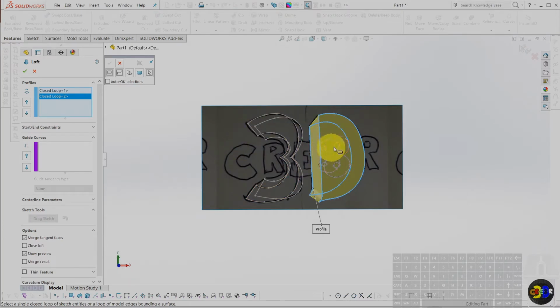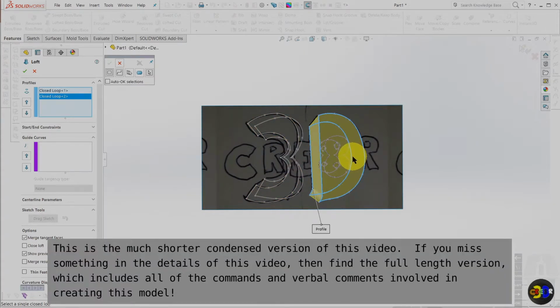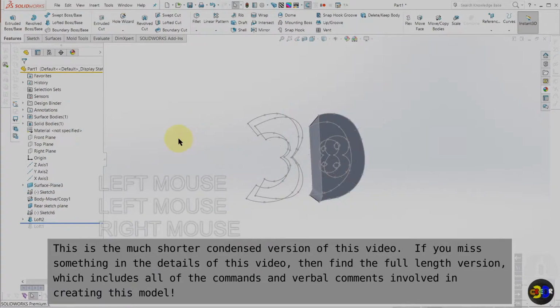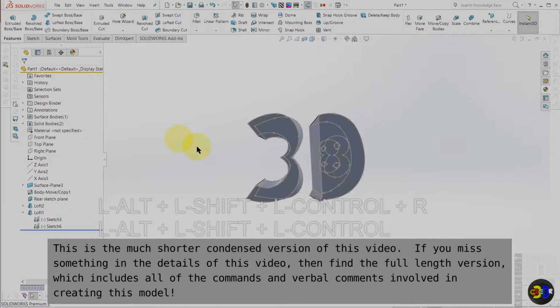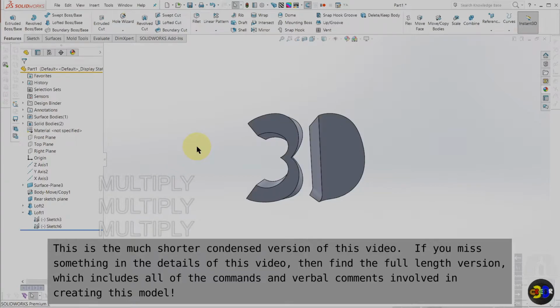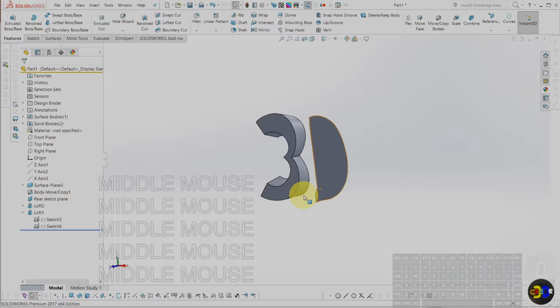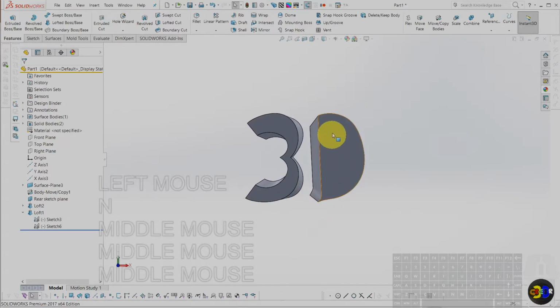Now I can't select all these individually to make one loft. I need to create multiple lofts, then do a Boolean subtraction to get to where I want to be. And so I will click OK there. And so now if I hide this again, and I roll to the end, and I hit asterisk, that's my sketches, kind of like plus is planes, asterisk sketches, so toggle it on and off. I want it off. Alright, so N for normal, so that's looking D for decent.